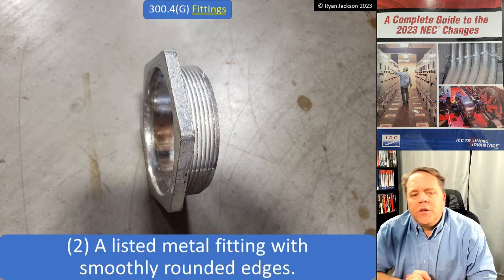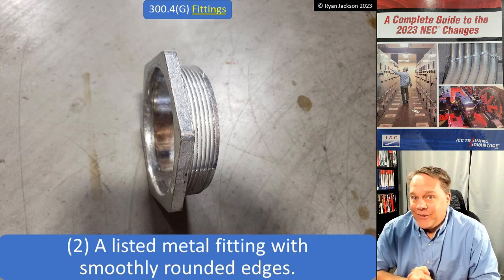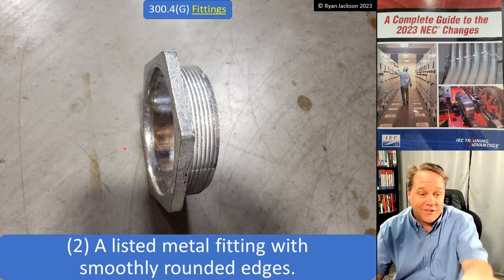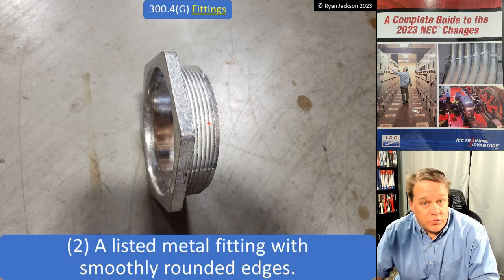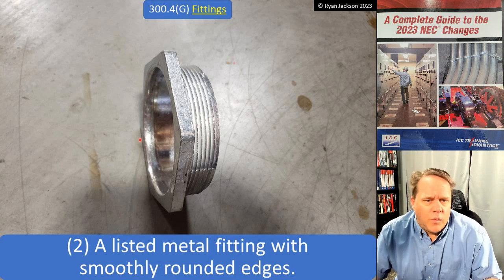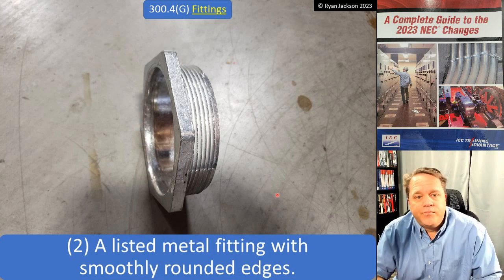Option 2, you could use a listed metal fitting with smoothly rounded edges. So a chase nipple like this, believe it or not, until the 2020 code, you couldn't use these for conductors 4 gauge or larger because it didn't specifically talk about it. It said you had to have a smoothly rounded insulating surface. Well, you're going to have a plastic bushing on the threaded side, certainly. But what about on the non-threaded side? That's perfectly smooth. There's no reason why I would need to provide any extra protection on that side of the fitting. And now, 2020 and 2023, we don't have to.